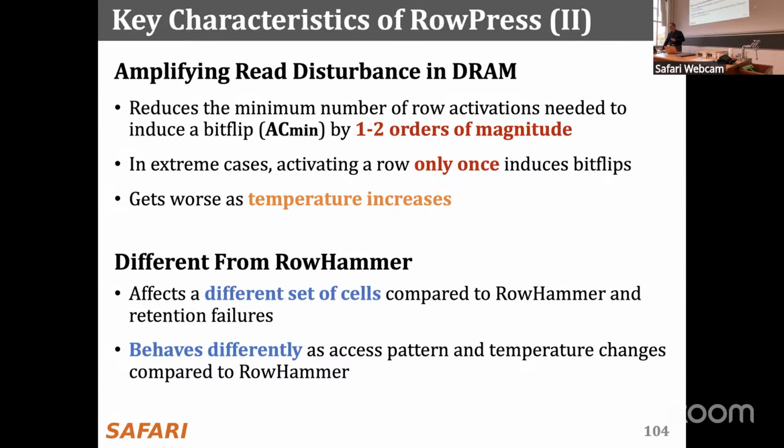Okay, so that's basically from a device level, from this FPGA perspective, yes, you need to keep the row open. And if you actually close the row after every activation, you minimize the amount of time and you're less vulnerable. That's true. But the problem is you don't exploit the locality in the row buffer if you don't have some sort of open row policy.